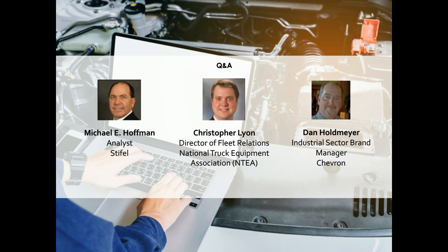If you have very few engines or old engines that you're not too worried about the life of, you could switch your entire fleet to the 10W30 if those newer engines allow a 10W30, but you do not have to maintain the FA4. I would recommend the API CK4 and look at the synthetic blend products. They do give you longer life and they give you better wear protection in those engines versus the traditional API CK4 and older oils. Thank you.